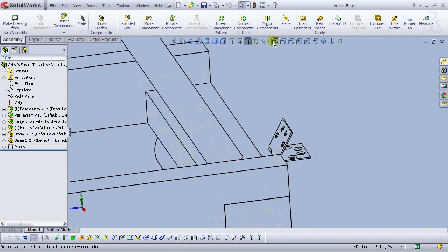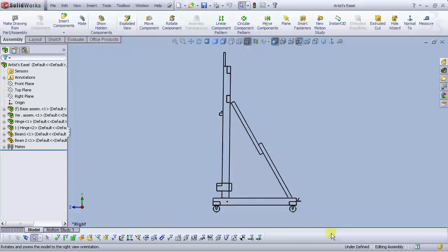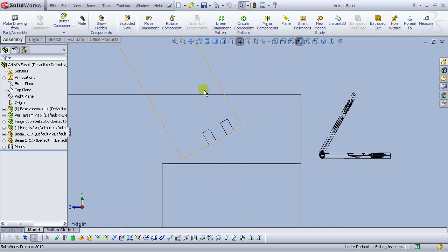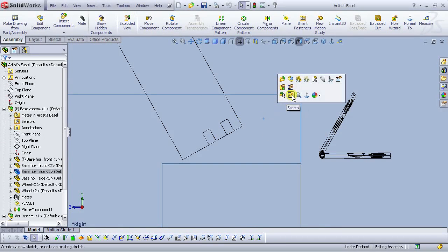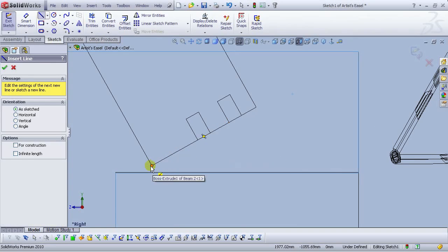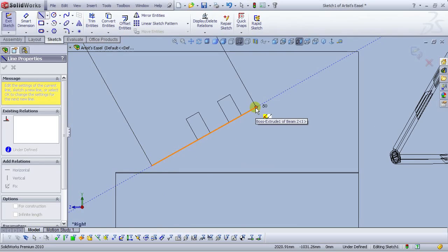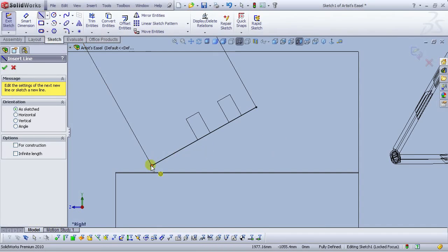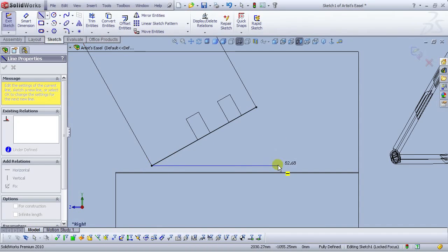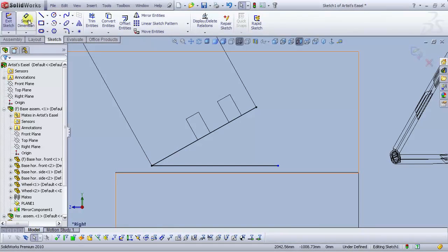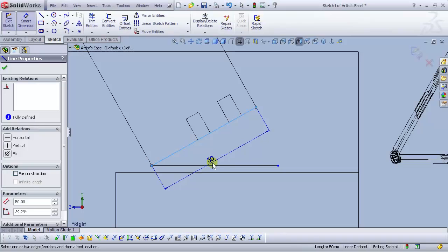and right now we are going to work on the right plane and select wireframe. Now select this face here and open a new sketch, and let's draw a line. Now I will show you a little trick for when something like this happens, how to draw a horizontal line. Okay, how to fix this?